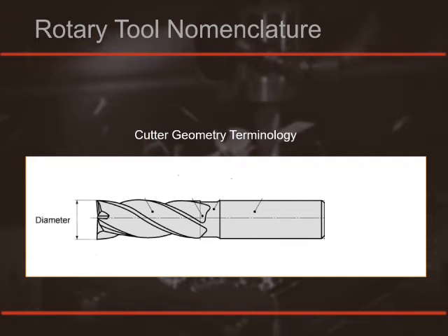They generally have a cutting diameter, which is the diameter of 100% engagement of the tool. They generally have flutes. They can vary in the number of flutes and style of flute. Some flutes are side cutting and some are merely to remove the chips from the hole or the workpiece. There's a cutter sweep angle, which can vary based off performance, number of flutes, and finish.